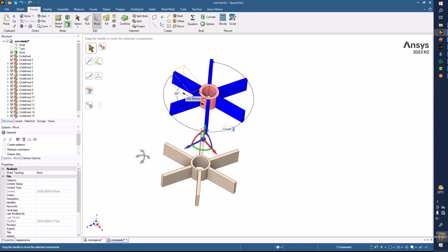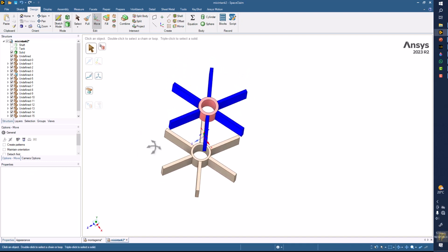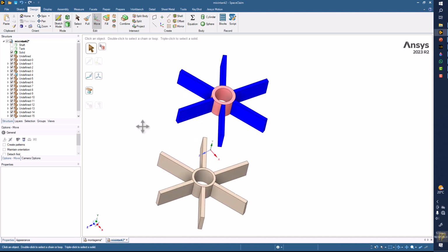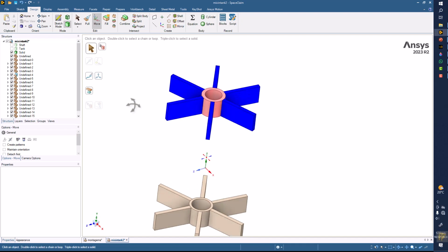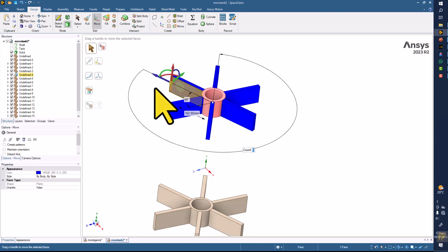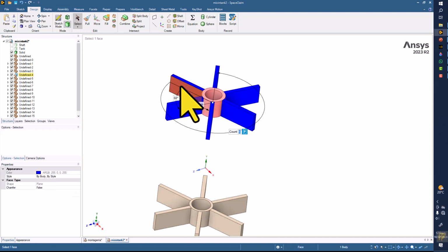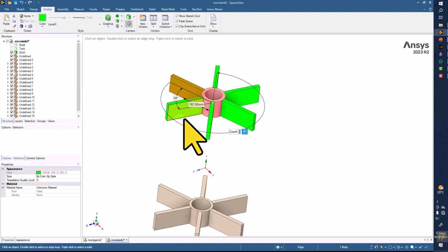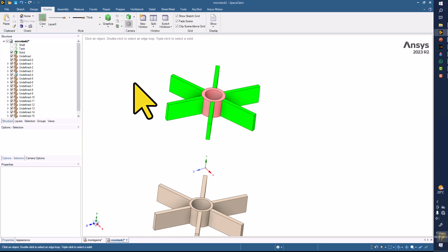So 6 parts are created here like this. Okay. So now you can put different colors if you like. For example, I can triple click here and put a different color here. But right now, because they are part of the pattern, they will not have different colors. So if you want to unpattern them, you can do it.